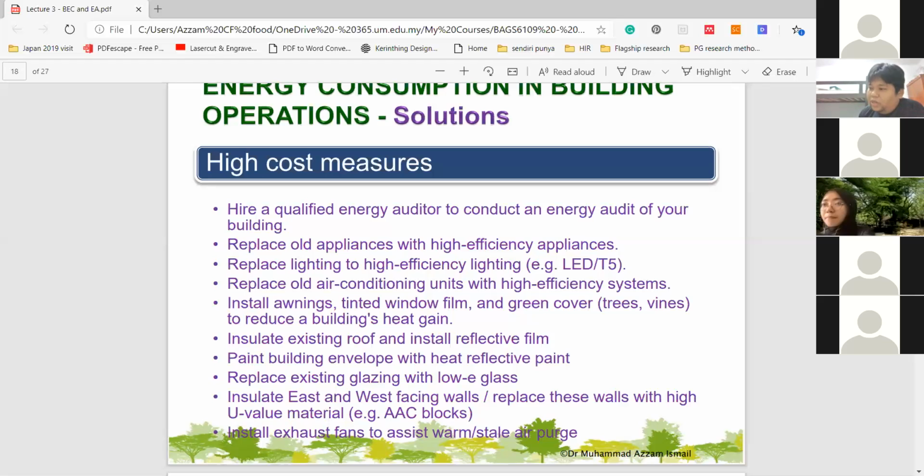Whereas if you go local, some contextualized kind of architecture, you use timber, let's say, or something very light, large overhanging roofs, you limit the amount of heat gain. You limit the amount of solar radiation, right? So you choose the kind of architectural language you want to use, okay? If you can, try to contextualize it, but nevertheless, painting will help. Painting will definitely help. If you paint your building with black, it doesn't help as well.